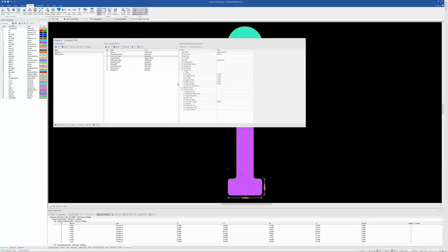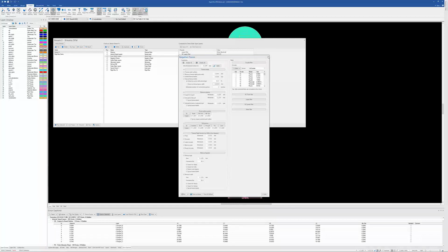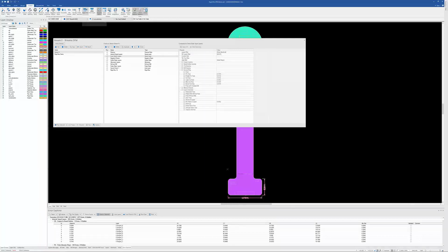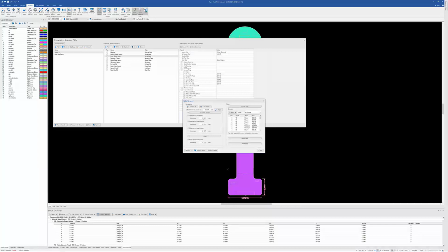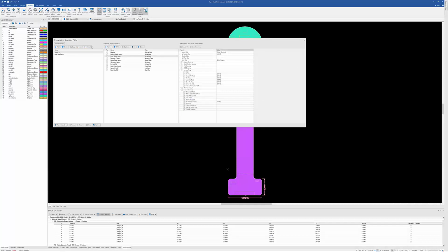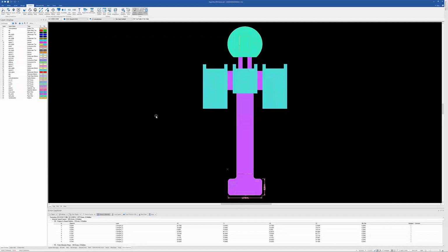So, I mentioned the negative planes. Here's all those negative plane checks. Or if you just wanted to make sure you're not putting silkscreen on solderable areas, you could just turn on this one check and run it and just check that analysis. So again, pretty robust in how we allow you to define the analysis that you're going to run on a design.